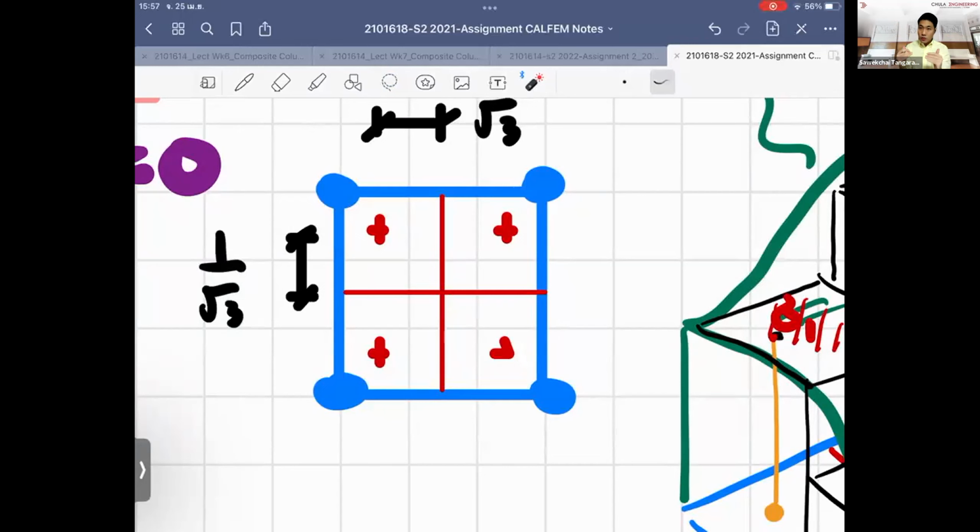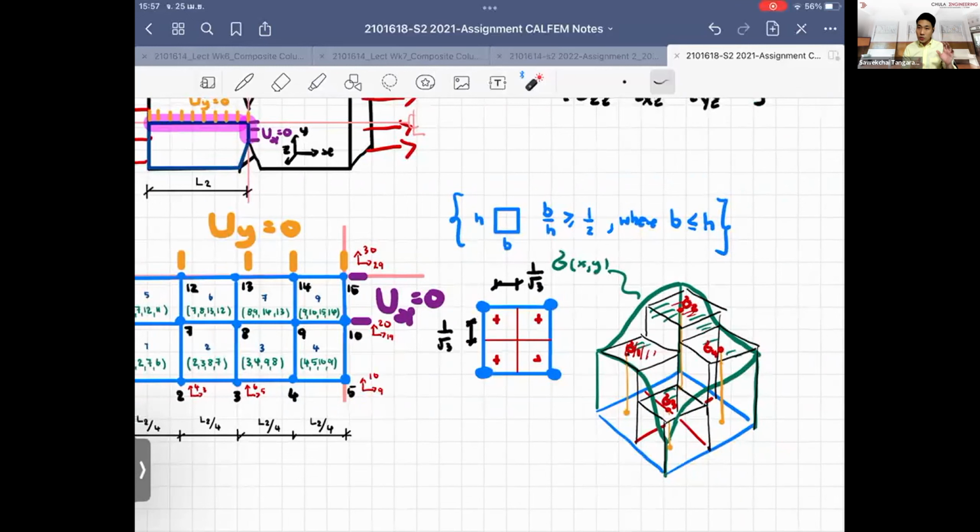There is a rule, theoretically proven, of how many Gauss points work for what order of the function in the displacement field that you assume. The more you increase the order of the displacement field, meaning a nonlinear shape function rather than a linear one, the more accuracy you have, but of course it takes more computing effort.